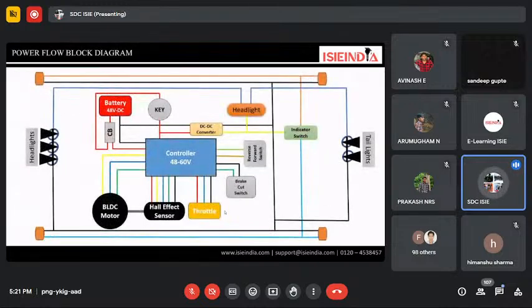I will explain the basic connections, because in a wiring harness it's very complex to explain which wire is for which component and how to identify it. When we talk about wiring harness testing, you can use a multimeter to check the continuity before connecting any device, like what are the input ports and what are the output ports. So you can check whether the desired output, after passing through the component, is delivered by the power from the battery backup power supply.